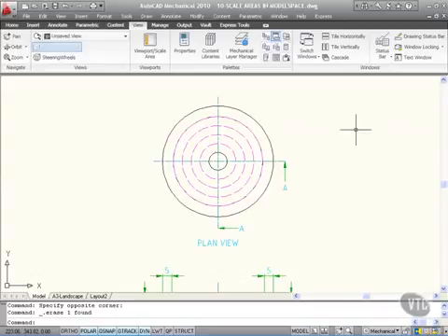Now you can automatically create a viewport from a scale area in Modelspace. So we're going to go down that road first and then create other scale areas and generate viewports from them. Make sure that you can see your plan view here in your drawing. Now the work file has 10 scale areas in Modelspace.